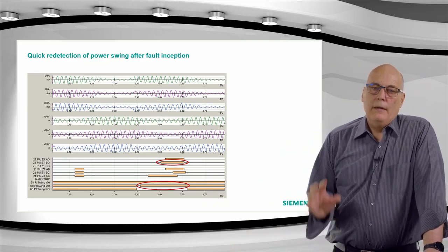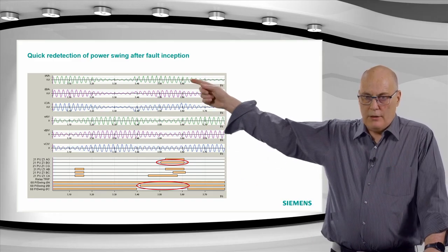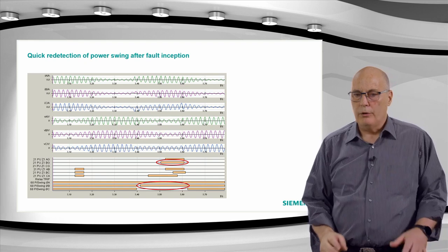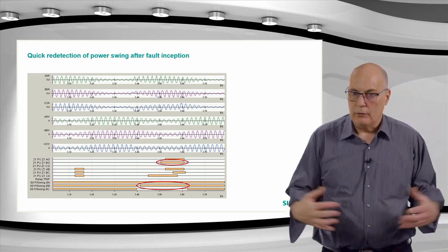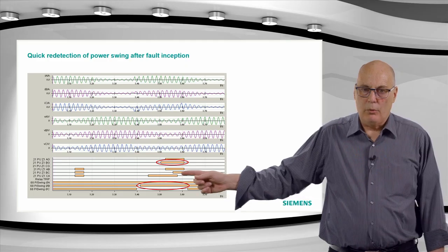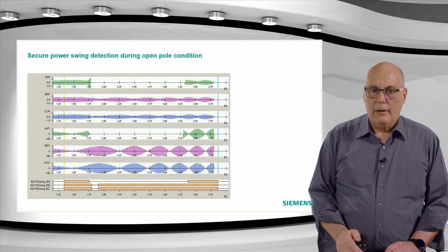Okay. In this model, the tripping was not done to the breaker. Otherwise, the current would have stopped. It would have a single pole dead time here, but unfortunately the model used at that time did not really trip the breaker. It was to show the zone 1 trip would have come. And on the other phases, the power swing blocking stays on over here. That is clear. It's one example.